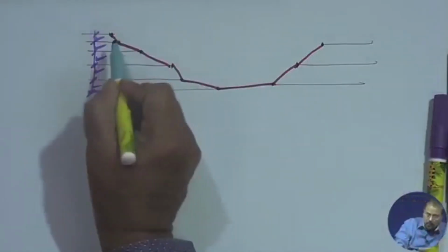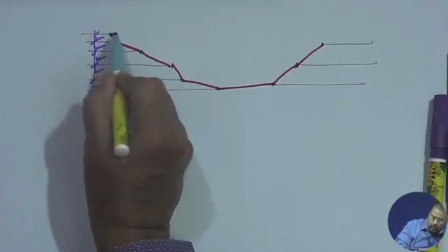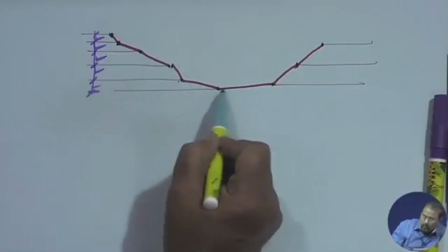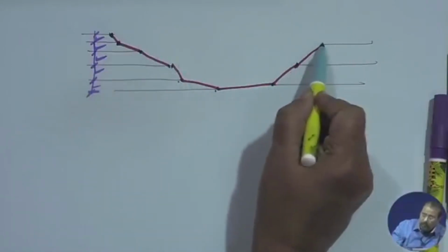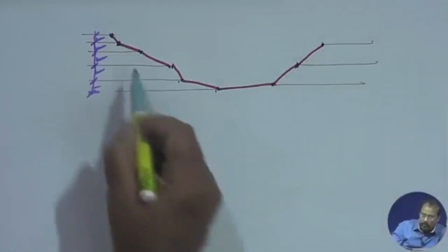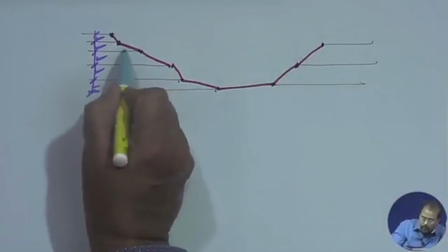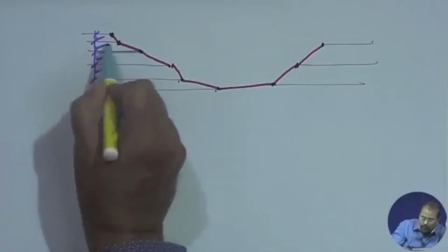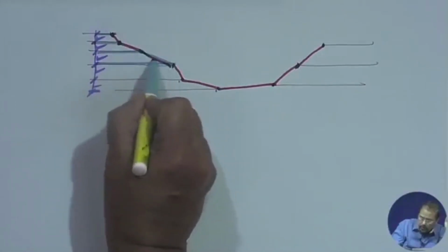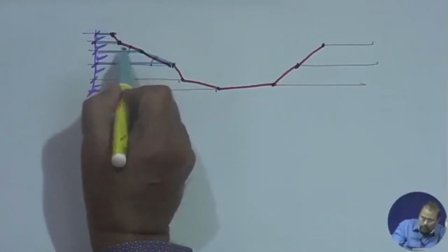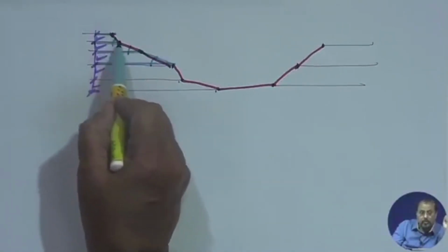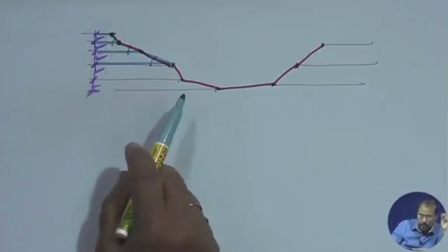That means the contour line, which is a cross section as a point, is at equal elevation down here and here, again up and up here. In this drawing you do not try to measure exactly the length, because I am quickly drawing it, but basically if this was the plate, this was the plate and this was the plate, then this particular line is at an angle here. You will see the higher the angle, the steeper is the slope of that particular surface.